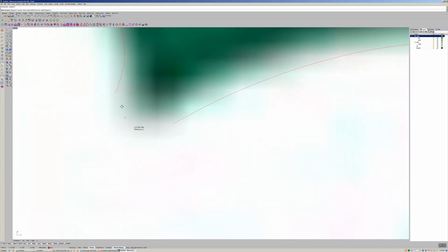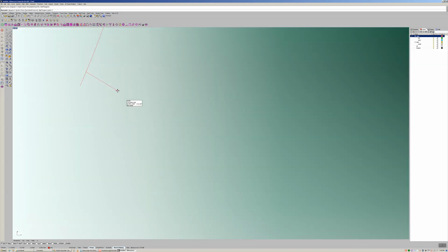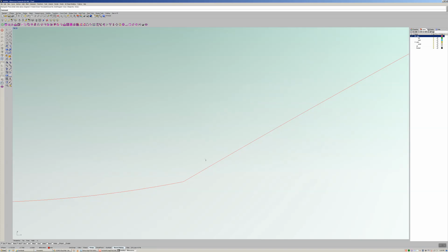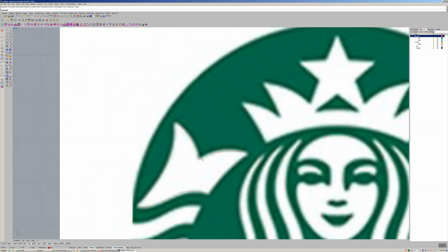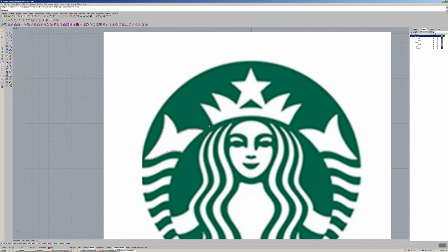So I'm going to right click, snap. Oops. Now you see I made a mistake. I'm going to zoom in so you can see the mistake. I overlapped and I didn't snap at the end. That's a problem. So I'm going to escape that because that's not a good spot to snap to. Right click, snap to the end. Click one more time, snap, and close. When you zoom in, we should be good. Yep, nice. So what we have here is our first section.